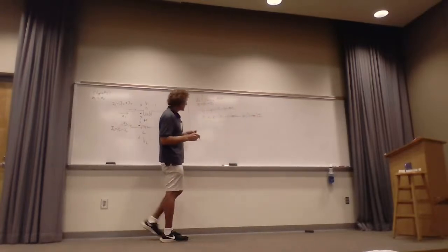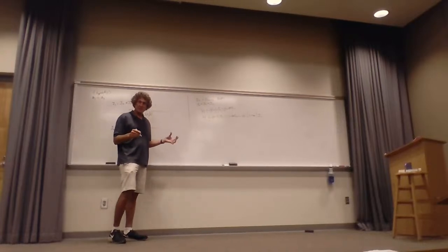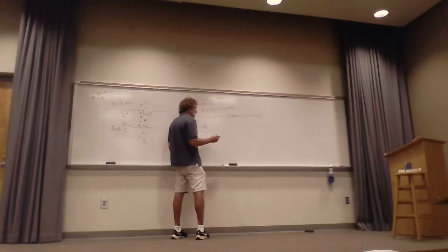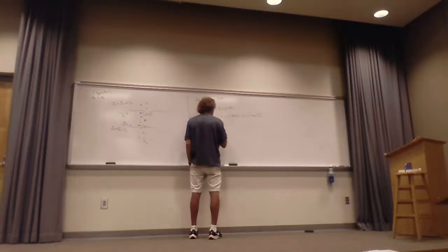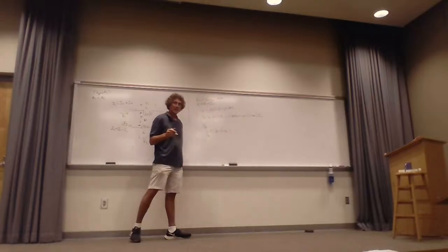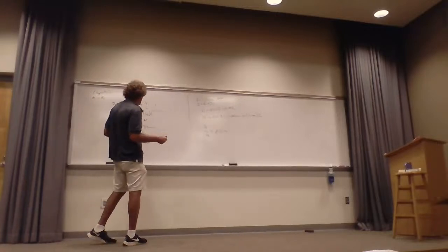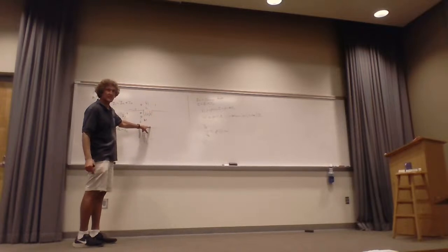Now this is just V1. Do y'all see that? Now if I want to think about an equivalent impedance of that, V1 over I common, that would actually just be j omega times L plus M, wouldn't it? And that would be the impedance of just this element. Now you can make an argument for symmetry that the impedance of this element would be the same, correct, class? So it'd be twice that.